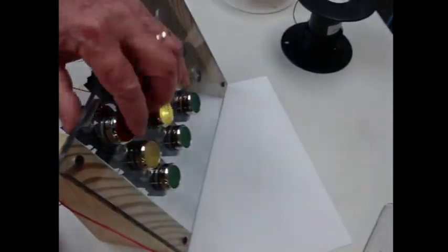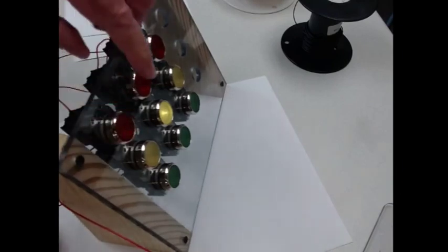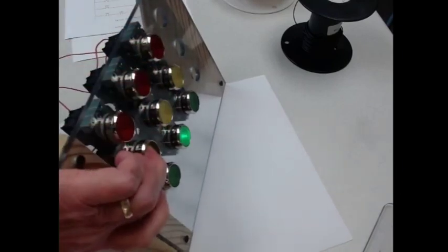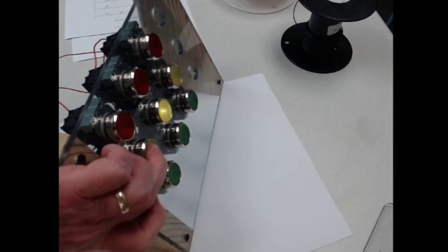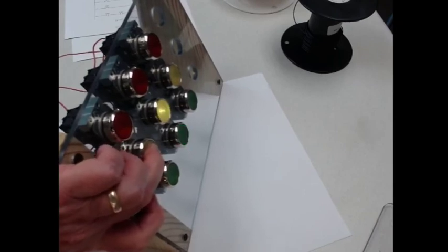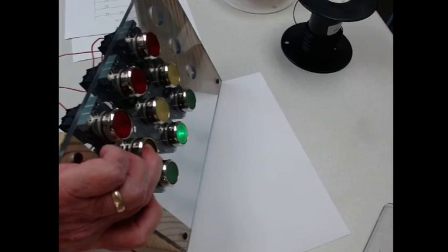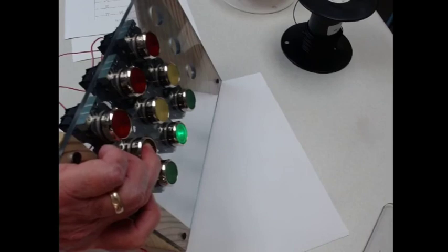So if I push the button, what happens? Whoops, got to push the right button, Ted. Look at the lights change the positions. So this is an example of wiring of a push button and then going through a relay, a CR, to turning on one light and turning off another light. That's the circuit at the top of page 32.